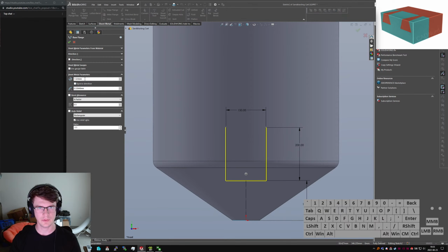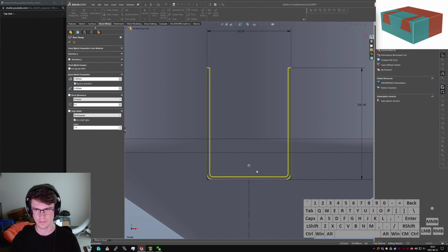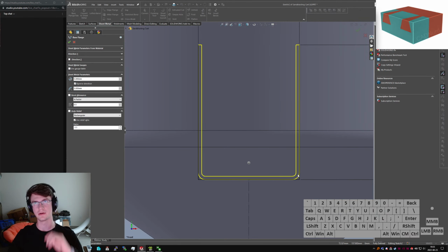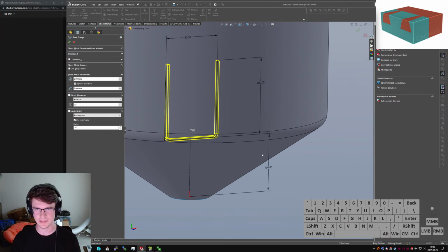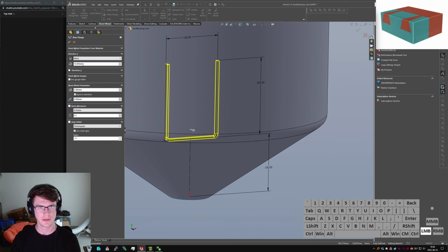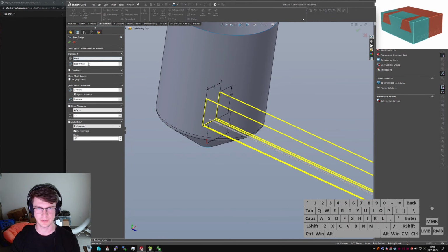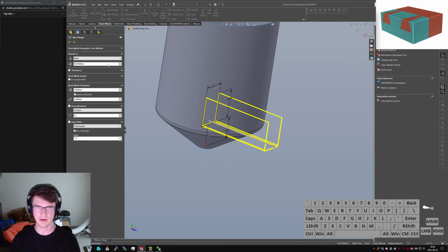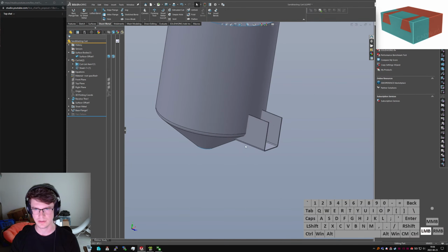And it's starting with what looks like rounded imperial numbers, so I'm going to say 5 mil thick sheet metal. And do the same for first direction, set a 5 millimeter on the interior radius. That'll be a pretty nice factor. So direction 1, what does 2 meters look like? Way too much. Okay. What's half a meter look like? That looks about right. So we'll call that good.